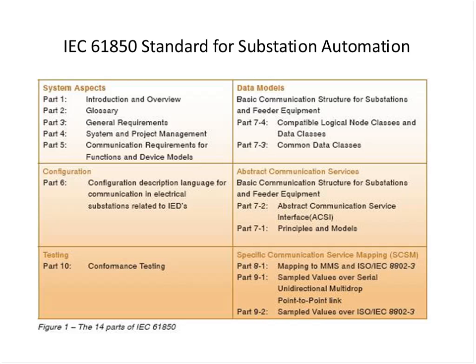And I have been going through this specification, and I have to tell you that after a while it hits you about how much people have thought before they went writing this, and how much it can support going forward, especially in distributed energy resources, and also equipment that has multiple services, and it has attributes associated with those services. This abstract object model, the layered model that 61850 has, is key to supporting such sophisticated implementations.